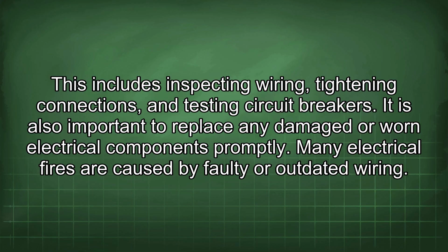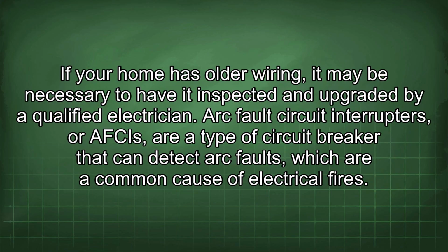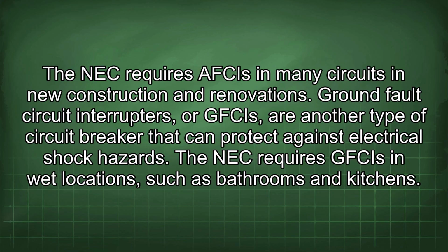Many electrical fires are caused by faulty or outdated wiring. If your home has older wiring, it may be necessary to have it inspected and upgraded by a qualified electrician. Arc fault circuit interrupters, or AFCIs, are a type of circuit breaker that can detect arc faults, which are a common cause of electrical fires. The NEC requires AFCIs in many circuits in new construction and renovations.